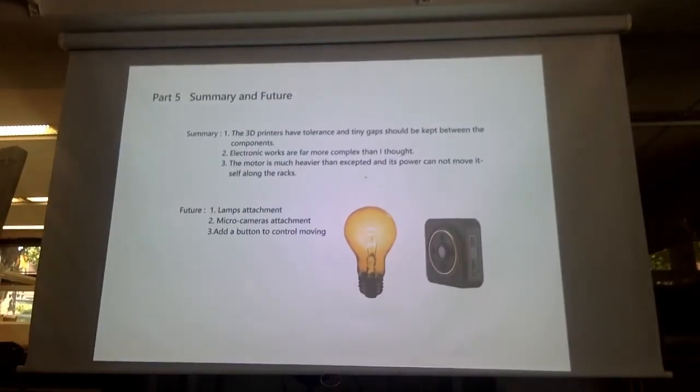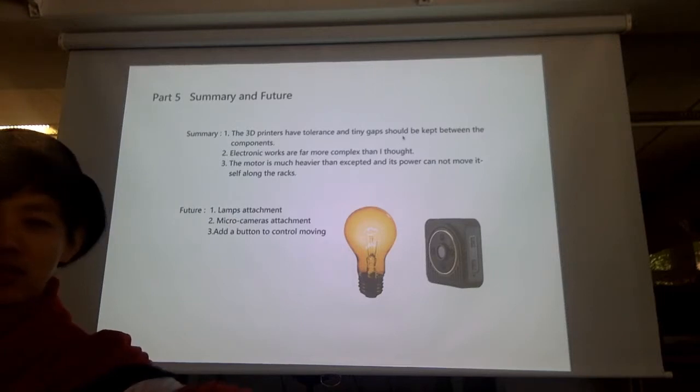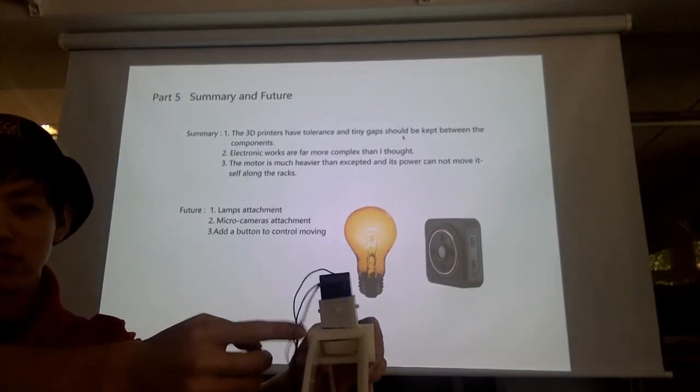But I have some summary: the 3D printers have tolerance, and tiny gaps should be kept between the components. At first I didn't build in tiny gaps, so the racks could not go through the instrument.